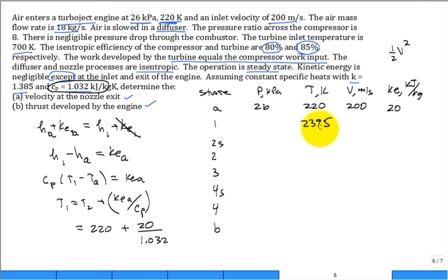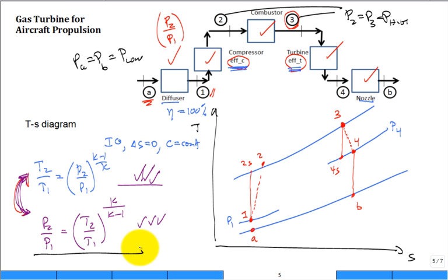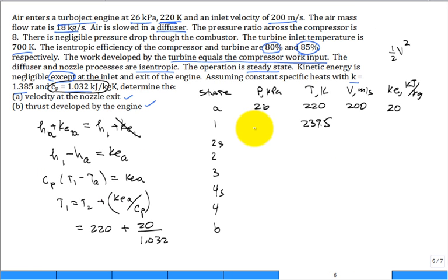P1. We already used the energy equation. Use the entropy equation. We did the first law, use the second law. But guess what the second law boils down to? Isn't that it? Hey, we just calculated the temperature increase in the diffuser. It's isentropic. Hence, I can get the pressure increase, the pressure at the outlet. So this pressure, and I hate to retype that equation, but somebody want to run that? It comes in at 35.2 kilopascal.